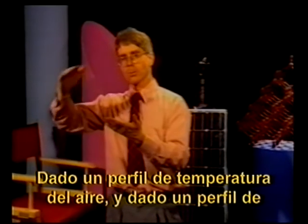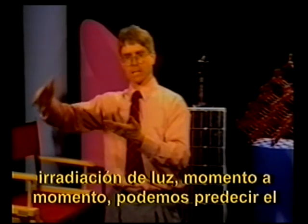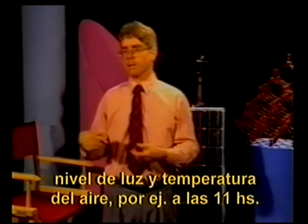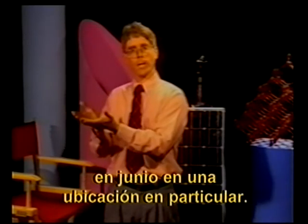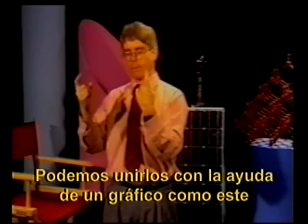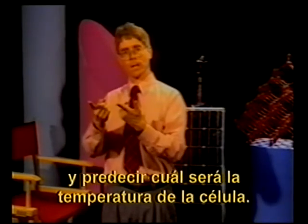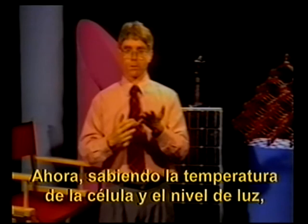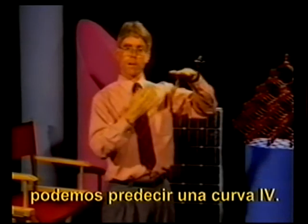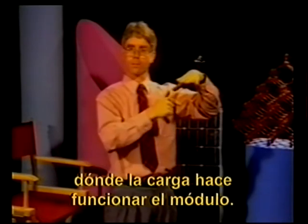Given a profile of air temperature, and given a profile of light irradiance, moment by moment, we can predict at, let's say, 11 o'clock in June for a particular location, what the light level is going to be and what the air temperature is going to be. And we can put these two together with the help of a graph like this and predict what the cell temperature is going to be. Now, knowing the cell temperature and the light level, we can predict an IV curve. And knowing the IV curve and the voltage of the load, we can see where the load operates the module.